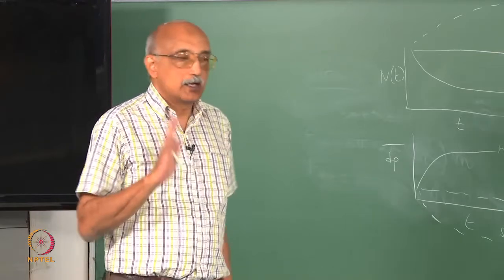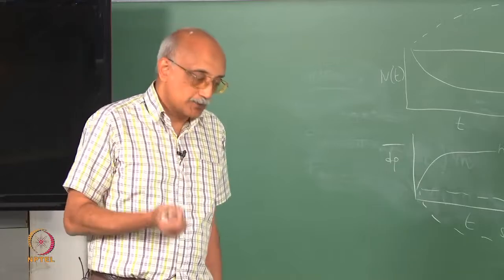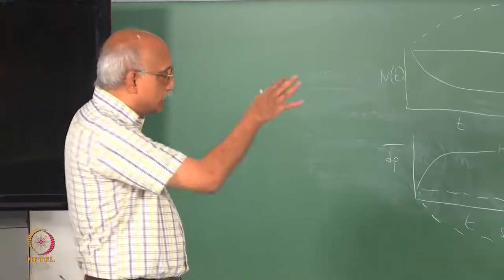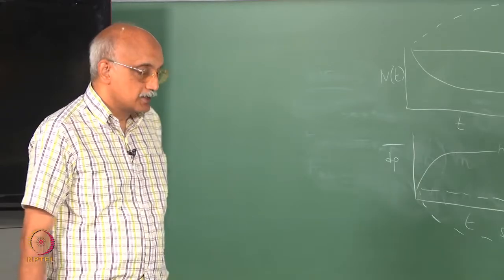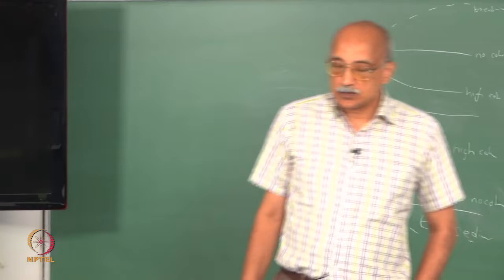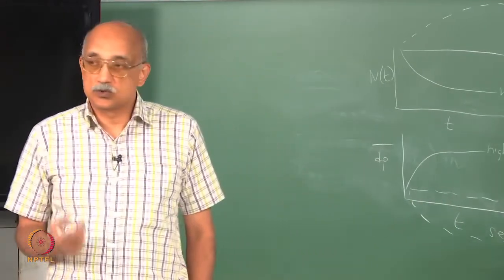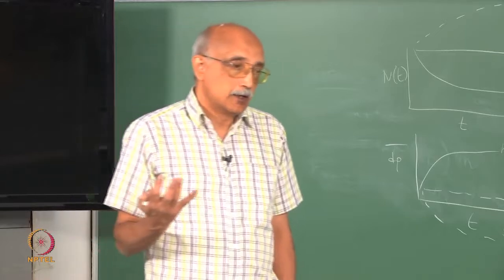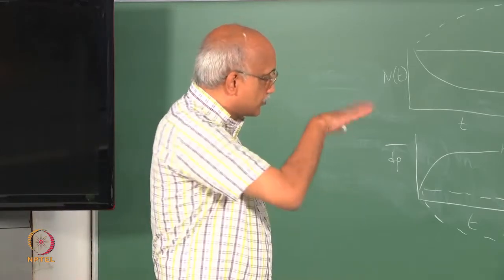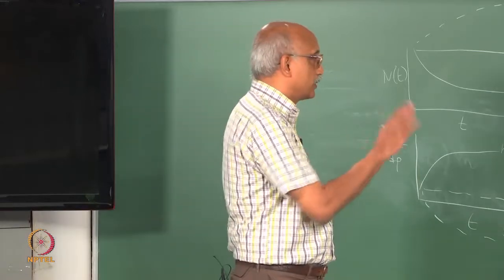Particle size, you may or may not be able to play around much, but in general realize that as particles become smaller, it is going to be more of a challenge to keep them apart. So, you have to do more playing around with the other parameters, and of course, viscosity. Increasing viscosity is a good thing, and there are certainly viscosity enhancers that you can use, or you can use solvents that are more viscous to keep particles in suspension longer. So, there are a lot of clues that you can get from this expression regarding how you can keep particles from cohering.